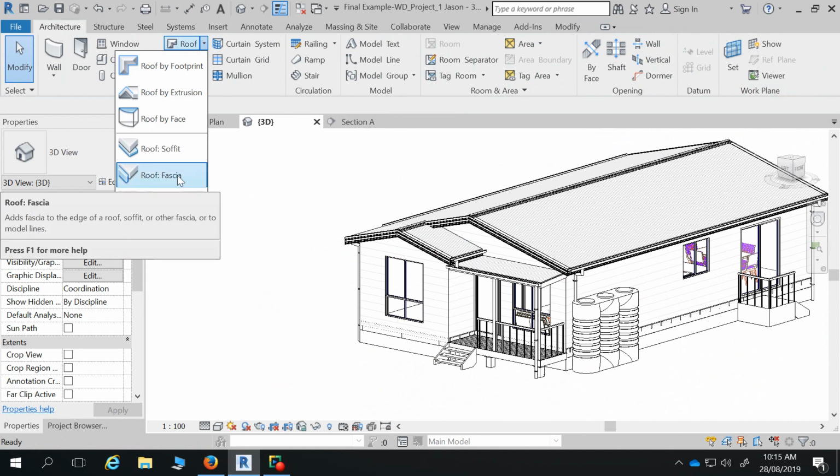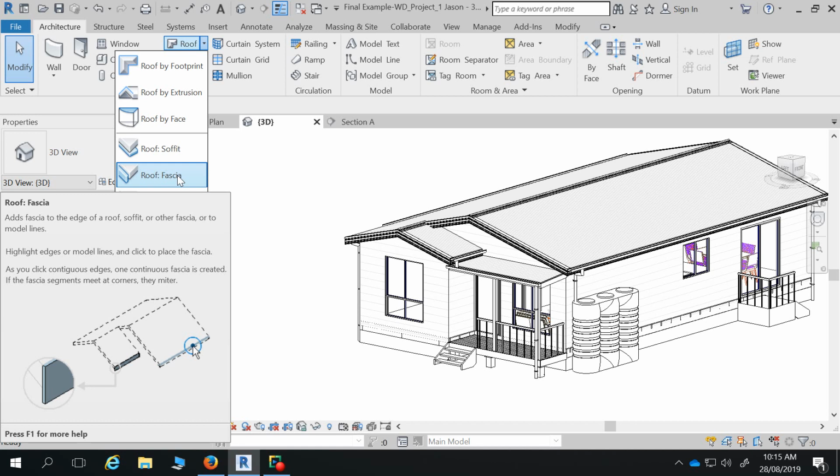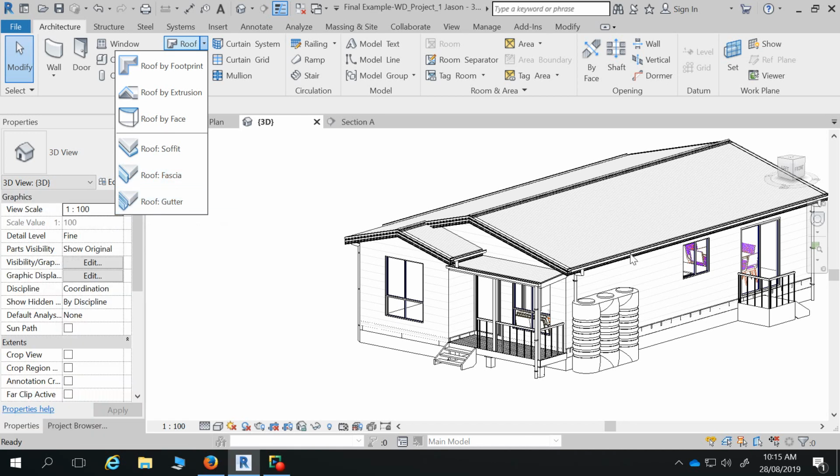fascia tool. So you know how when we did the fascia on here and then we did the barge board, we used the same tool but we changed the two profiles? Exactly the same thing. I make a third profile, duplicate one of those fascias and call it ridge capping, and that one's got that third profile loaded in that I've sketched, that shape that I just told you.